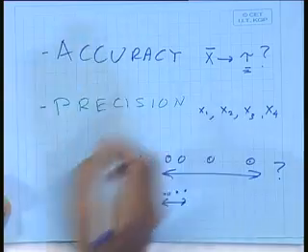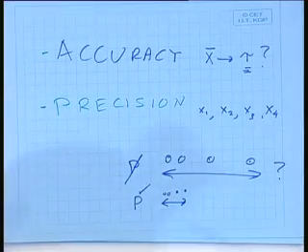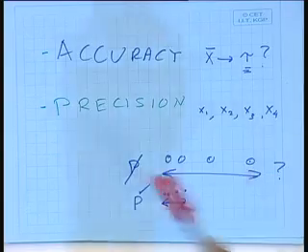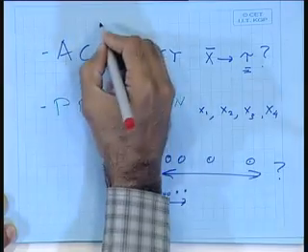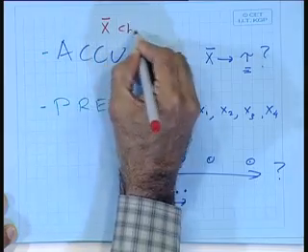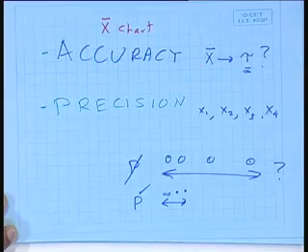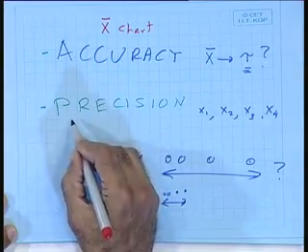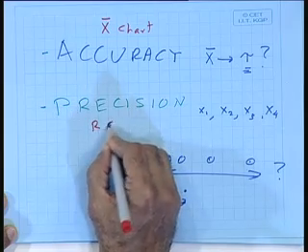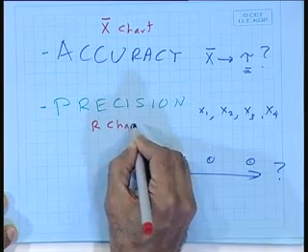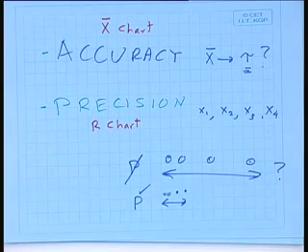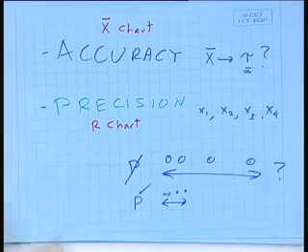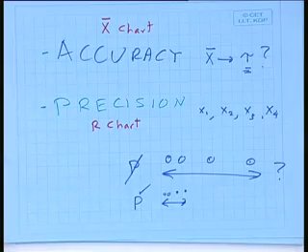When it comes to accuracy, we want to make sure our processes stay in control, that they are accurate and also precise. To make sure that a process is accurate, we use the X-bar control chart. And to make sure my precision is there, I use what is called the range chart, or the R chart. The R chart will make sure that you are able to get precision in the delivery, on the output side of the process, which I'll discuss again when I get to SPC. You just be aware of it.